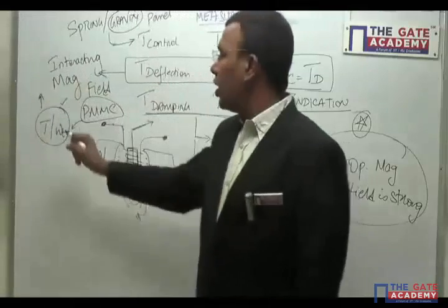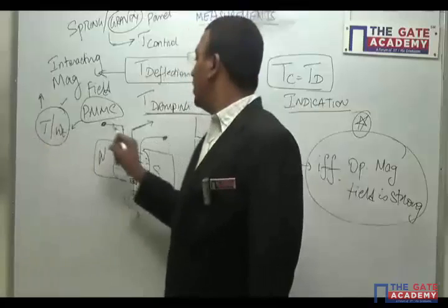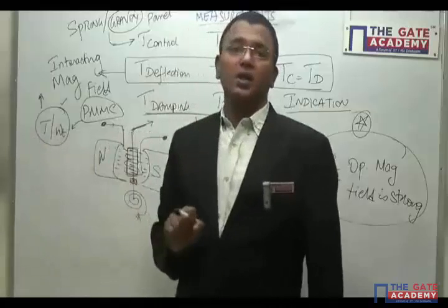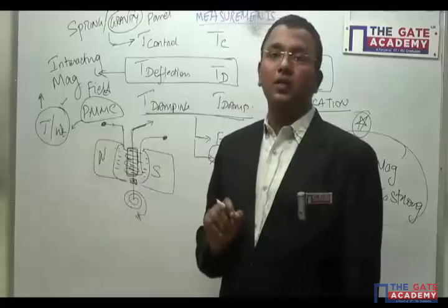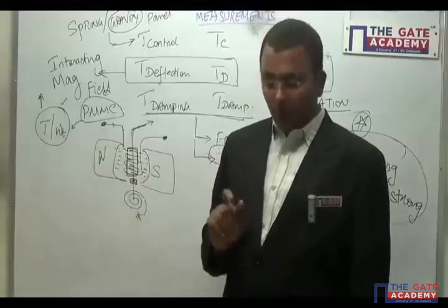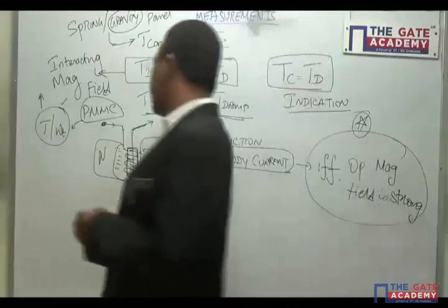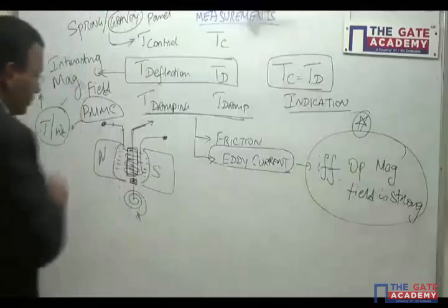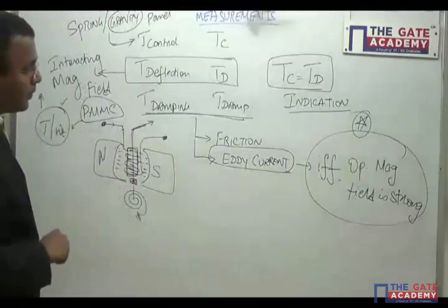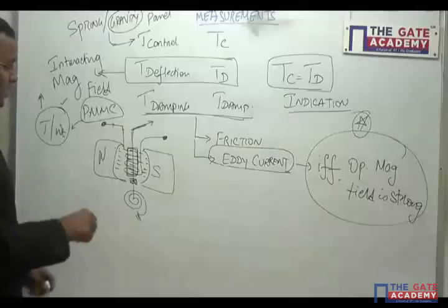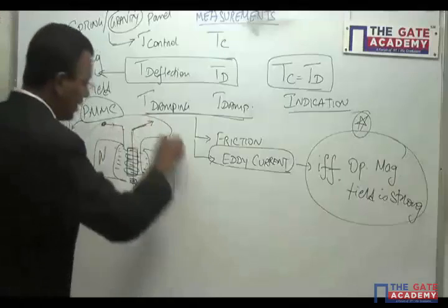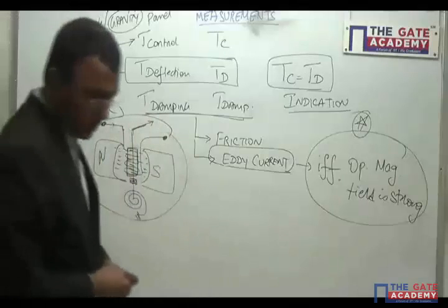The high torque to weight ratio means your instrument will not be sluggish. It will have a very good time response and frequency response. Clear? Then this is what we discussed yesterday. Let us get into the details of the PMMC instrument further.